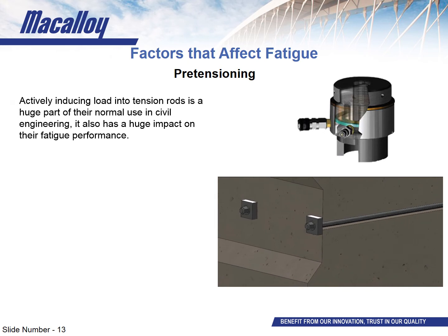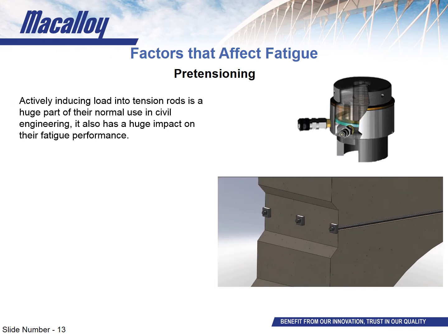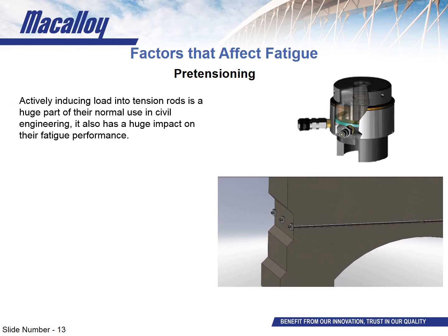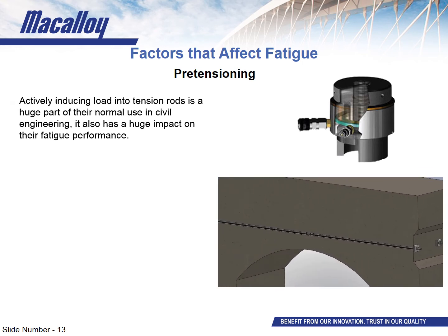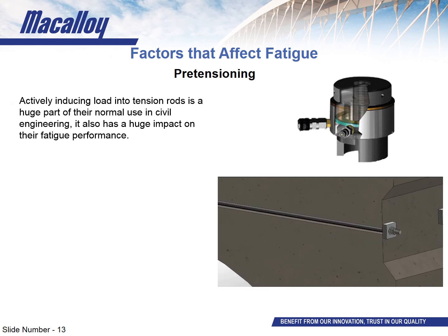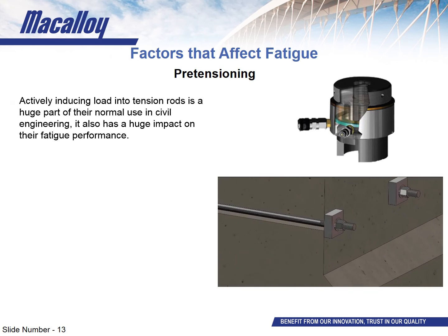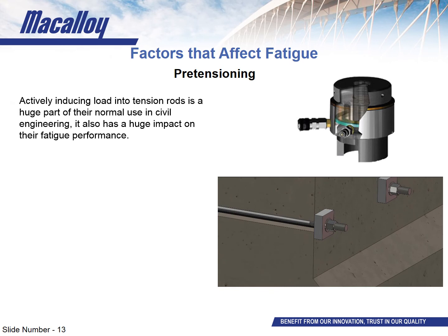The video playing now is a good representation of what the actual post-tensioning procedure looks like, or the pre-tension as I mentioned in the slide there. So we're panning around now to the live end or the jacking end where the actual tensioning is going to be performed, and then the equipment's going to fly in one by one and show you the procedure. So first of all, you've got the ring spanner, which allows you to rotate the nut. Then you've got the bridge coming in, which actually gives access to the ring spanner, the jack that provides the force, and the puller that connects it all together. That puller is then pushed outwards by the jack, and then the nut is rotated via the ring spanner to lock that load off.